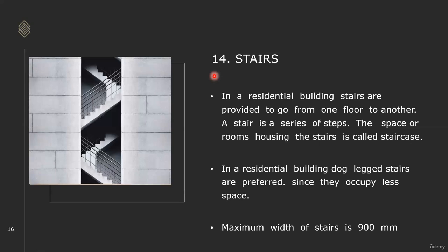Whatever things we are going to set on the ground floor, we set that, then we can go for the upper floors. So in those cases, we provide internal staircases. In some cases, we provide lifts also, bullet lifts, inside the particular residence. And always remember, whatever the bylaws are for that particular site area, we need to consider them. We need to understand what the minimum setbacks are that we need to leave from the boundaries, and then we can go with the planning.